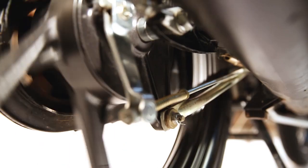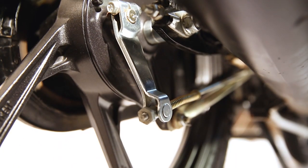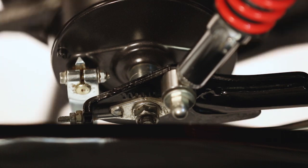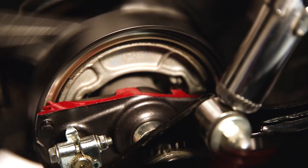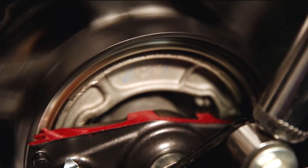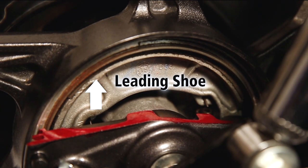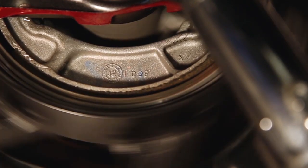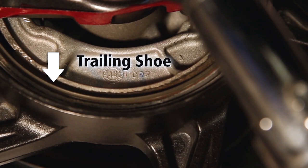When the brake is operated, the motion is transmitted by a cable or a rod to the brake arm. The brake cam is turned and this expands the brake shoes. The shoe which is expanded in the direction of the drum rotation is called the leading shoe. The shoe which is expanded opposite to the direction of the drum's rotation is called the trailing shoe.